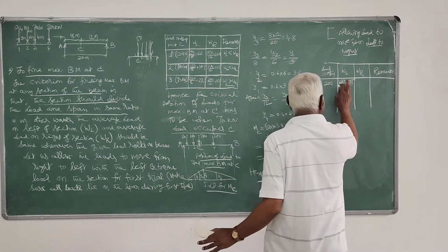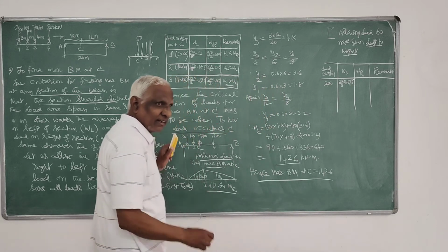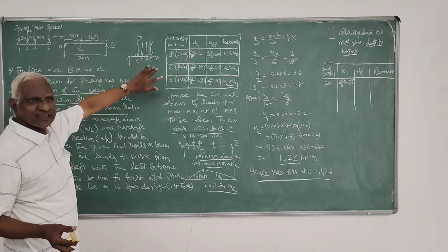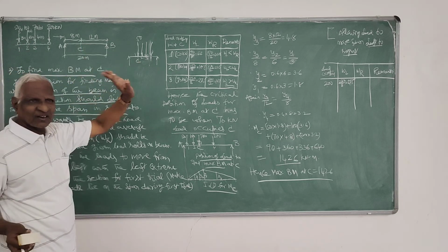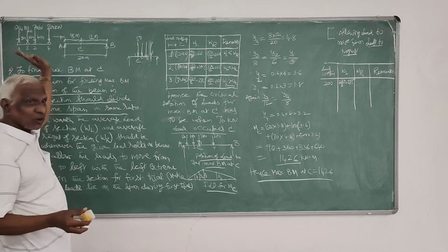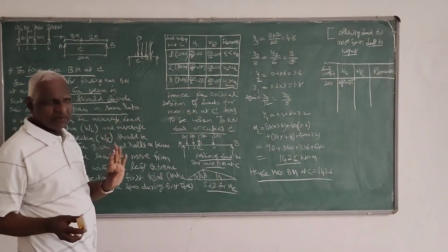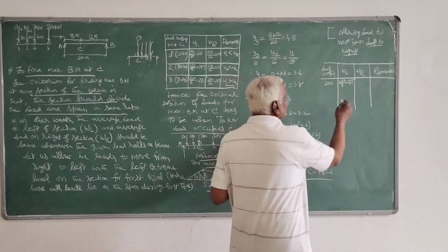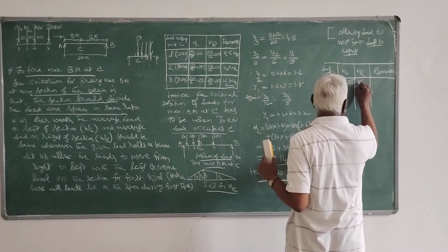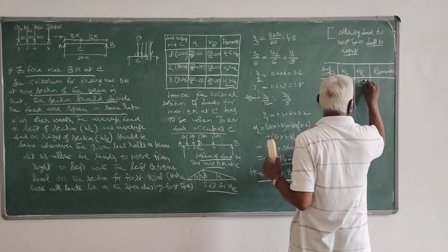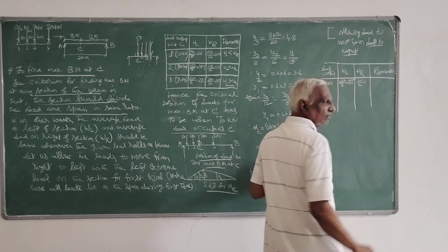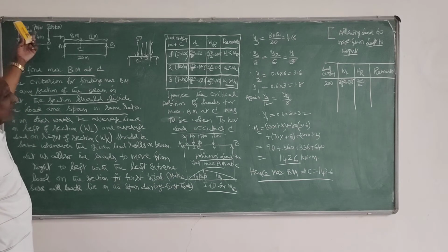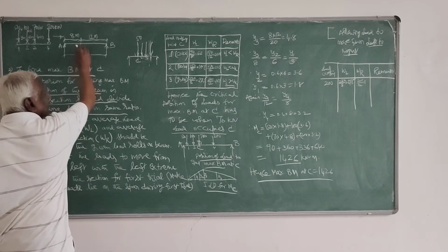So I am considering all the loads. Naturally, because when I say 200, they are considering on the other side, so naturally all the loads will come. Suppose if you have one more load, then it may not give maximum result. Here, of course, you can consider both. On the left side, that 50 kilonewton will not come, so only 170 divided by 8. 50, 100, 70.